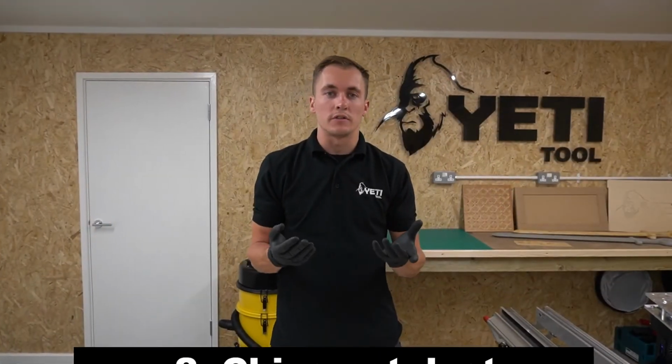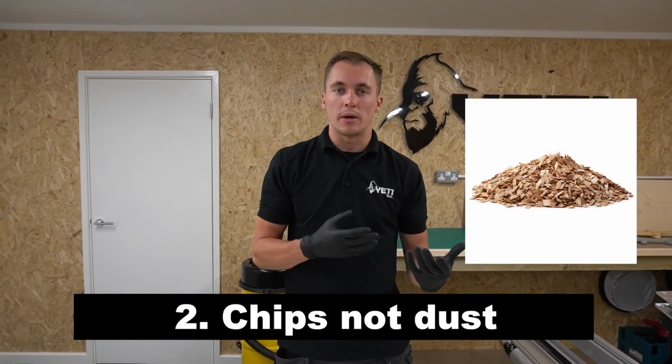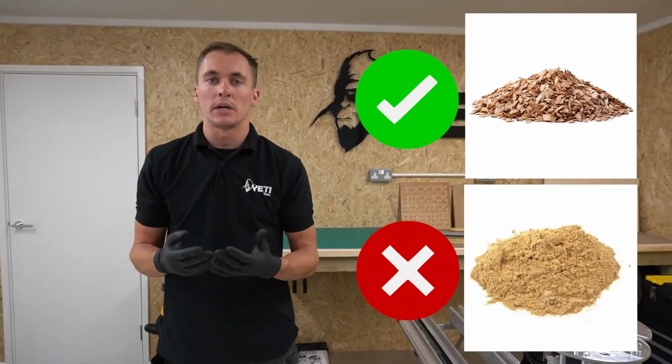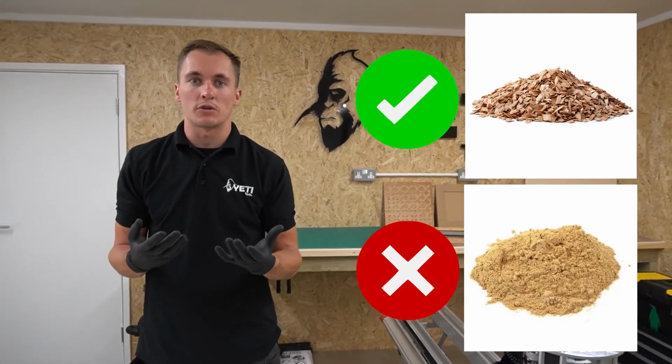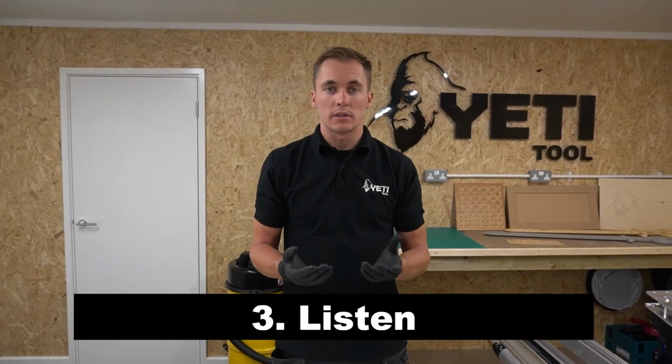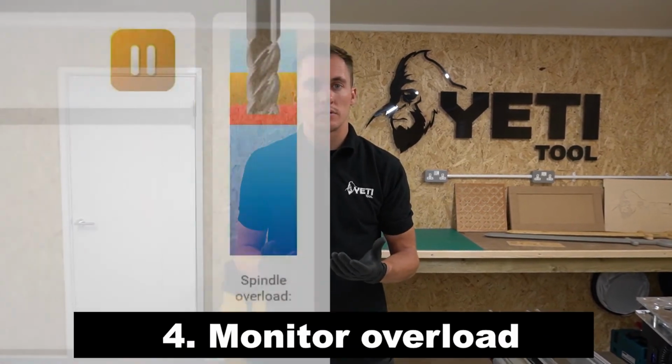When you're honing your feeds and speeds, ensure you're making chips, not dust. Chips help take the heat away from the material and improve tool life and finished edge quality. Always listen to the sound of your tool as it's cutting. If your cutter is struggling, you will generally hear a higher pitched noise.